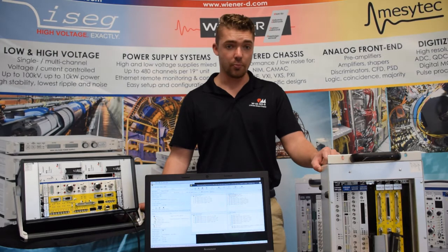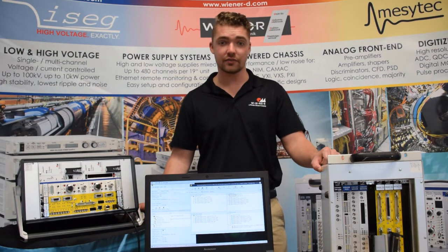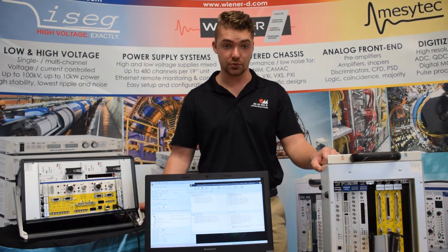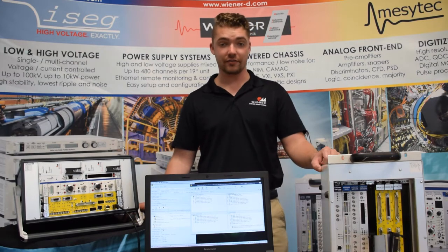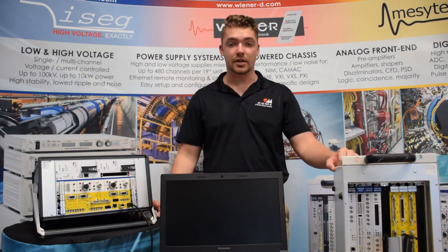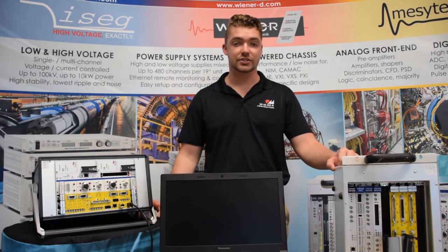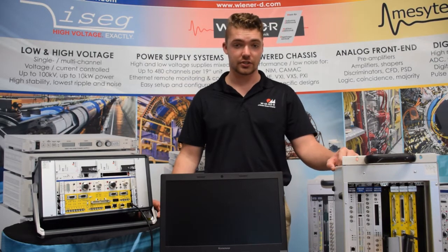It also has an open architecture allowing integration of other manufacturers' VME readout modules, and has an open software interface to export data from the analysis to professional packages such as ROOT. So why VME? We chose to go with VME because it is the most commonly used open bus standard in nuclear and high energy physics, along with a list of commercially available readout modules for your DAQ system.